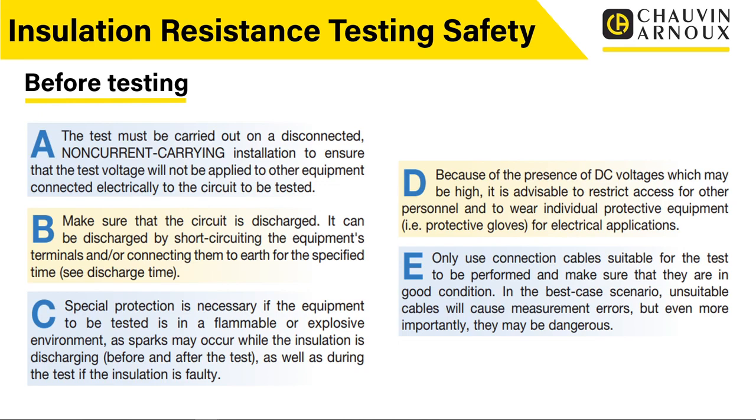The circuits must be made dead, and we should follow the full safe isolation procedures and lock-off procedures before we actually carry out insulation resistance testing. This is a dead test, for want of a better term. It's not carried out on an installation that's connected to its supply. It is not a live test, it is a dead test.